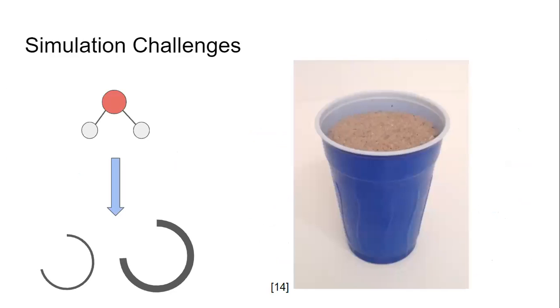There are a couple problems with these types of simulations, or specifically the software. They're great for force calculations, but they're not great with making complex particle geometries. And so what I have to do is create sets of points using Python, and then import those points into LAMMPS. There's also a problem where rounding errors through the time steps can actually end up adding energy to the system and create non-physical solutions.